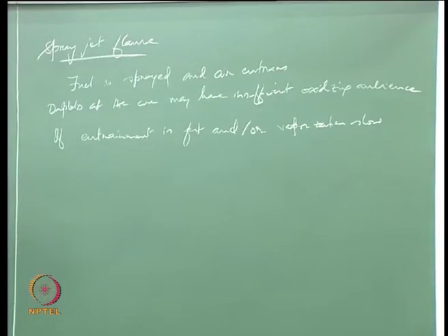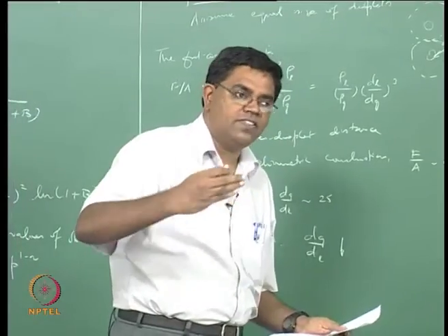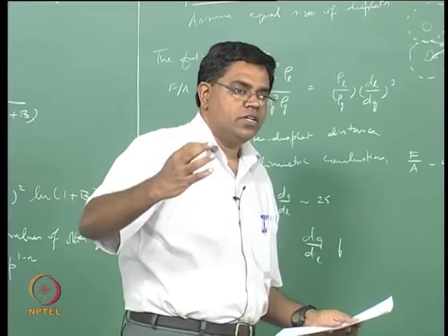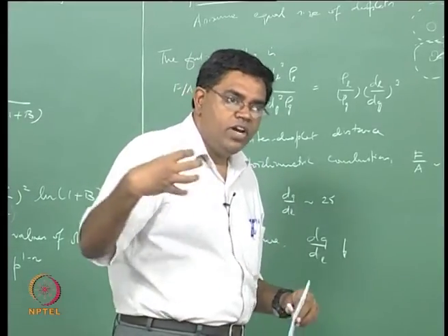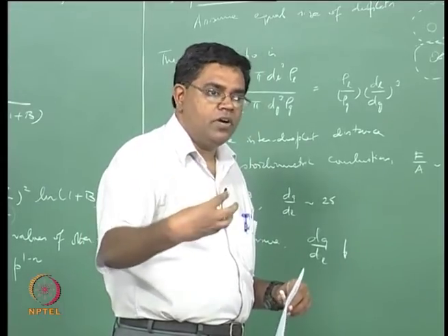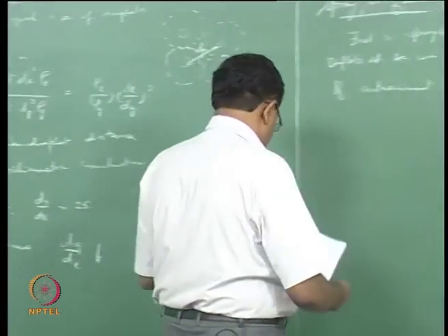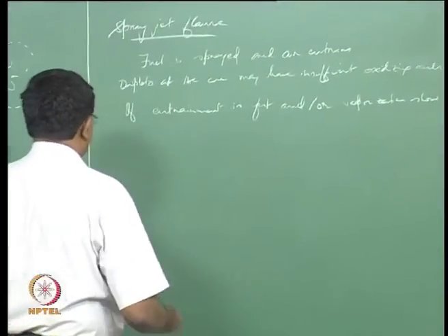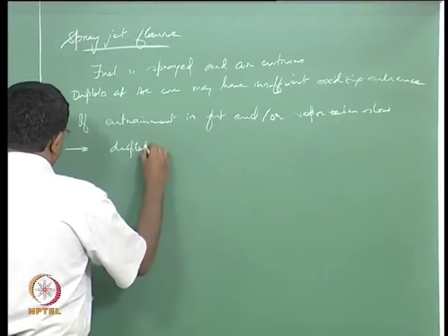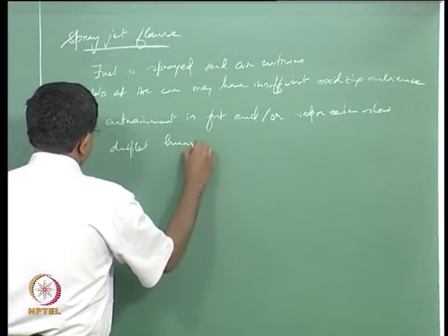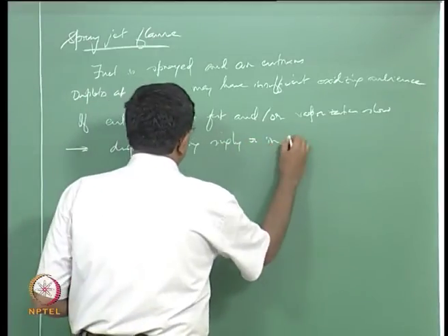Air is now beginning to get available to most droplets, and therefore most droplets can burn by themselves. They are harder to evaporate, therefore they are going to be waiting for the oxidizer to come near them and the flame to happen near them. So this leads to single droplet burning, droplets burning singly or in groups.